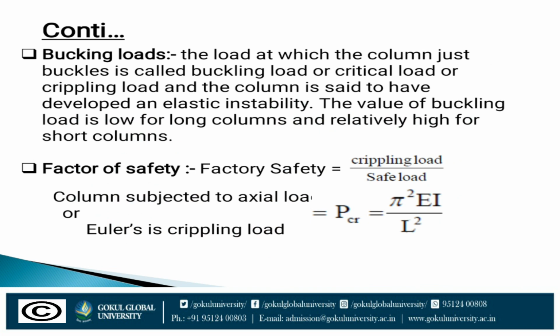Buckling loads. The load at which the column just buckles is called buckling or critical load or crippling load, and the column is said to have developed an elastic instability. The value of buckling load is low for long column and relatively high for short column. Factor of safety is equal to crippling load divided by safe load.